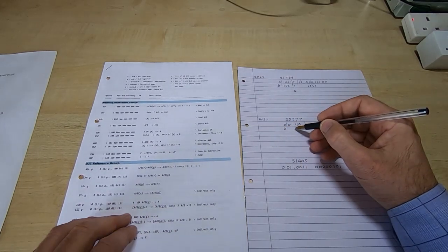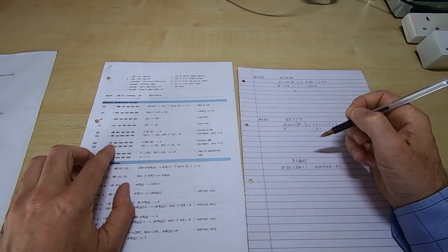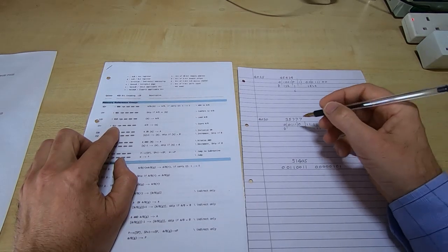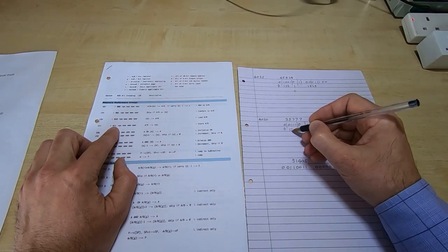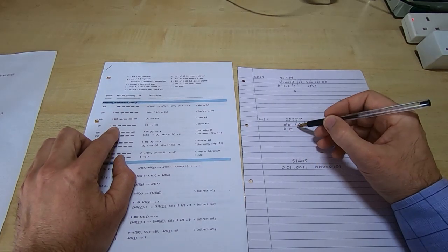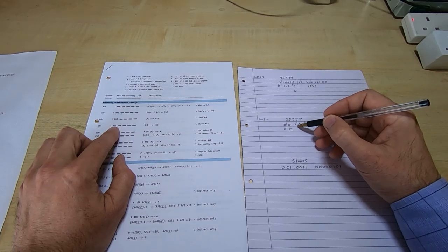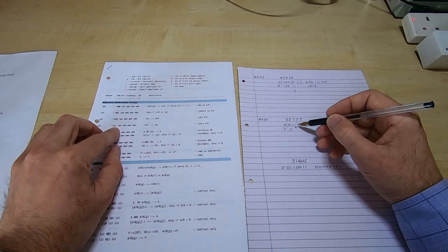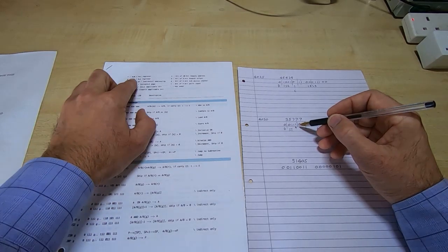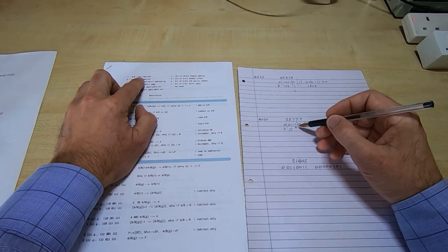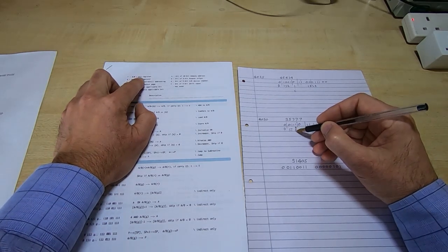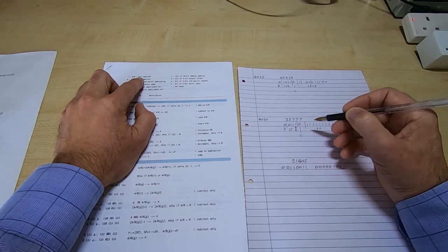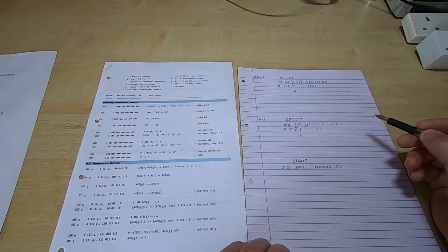The instruction itself, if we look for that particular instruction, we can see it's a store, and it's a store of either A or B. This bit is going to determine whether it's A or B, and if we look at the code for that, it's R, and if we look up here, A or B, 1 is B. So in other words, the instruction is store B, and again we're using the current page if we need to use the address.